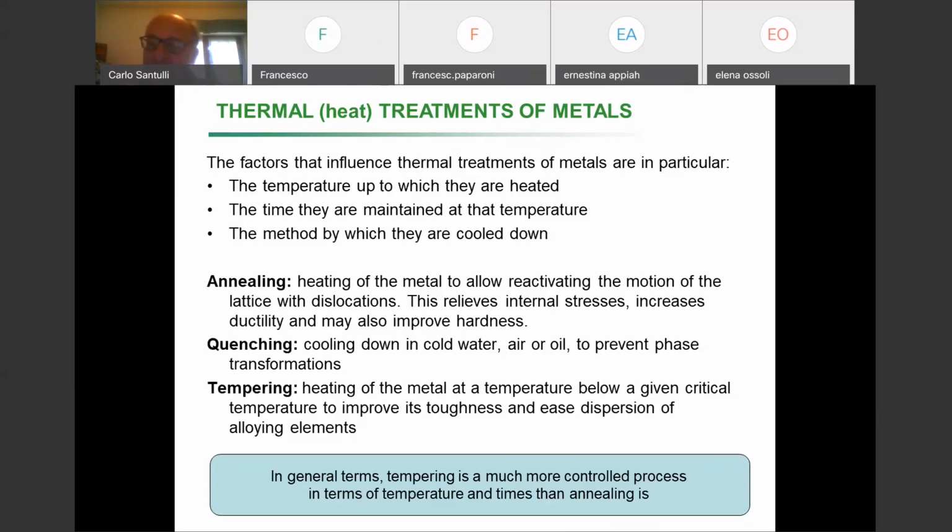Remember that the toughness is the resistance to a defect, to the presence of the defect. The fact that the defect doesn't expand, doesn't grow, especially doesn't get to that critical energy that allows the defect to proceed to fracture.